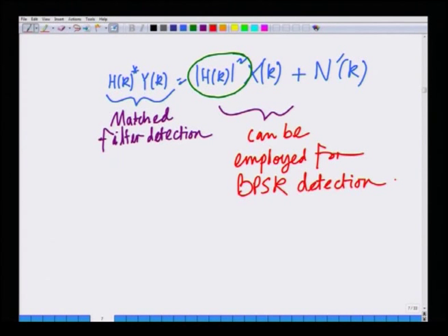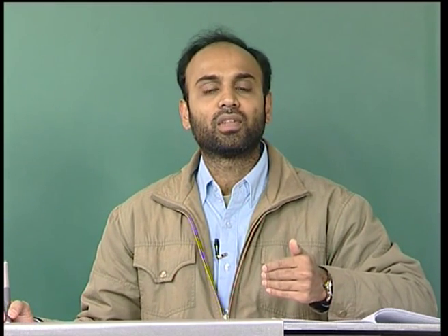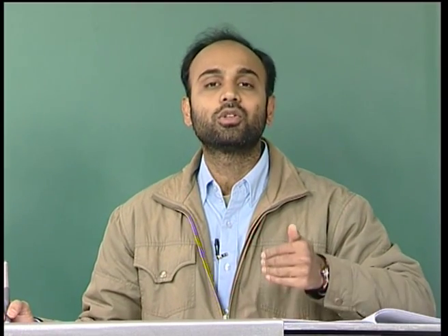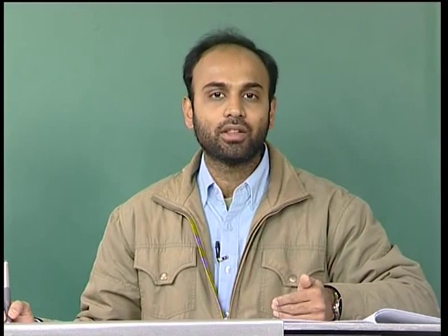So this can be employed for BPSK detection, and of course one can also be slightly more fancy and slightly more technically involved. As we said, zero forcing results in noise enhancement. Match filtering is not optimal in the case of high SNR scenarios. So what is the optimal thing? The optimal thing we already saw in the case of MIMO communication systems is the MMSE receiver, and one can naturally employ the MMSE receiver.